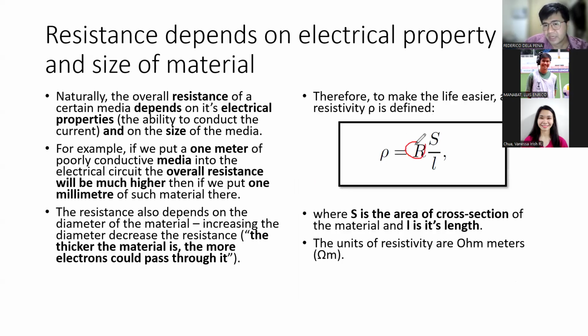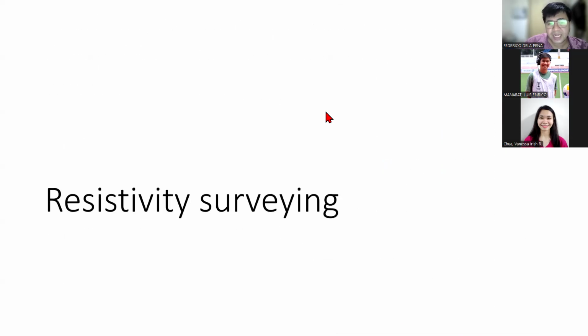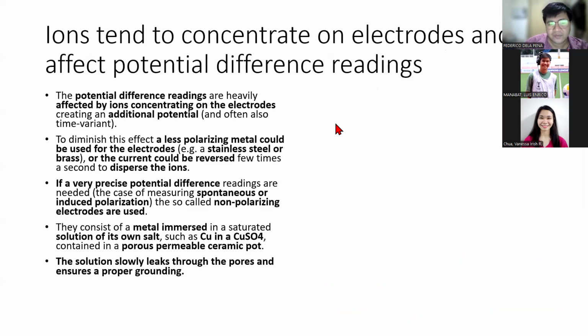From the resistance, we can determine the resistivity as long as we know the geometry of the flow path of the current. But we don't really directly know the diameter and length of the pathway. Instead, we use a geometric correction factor.